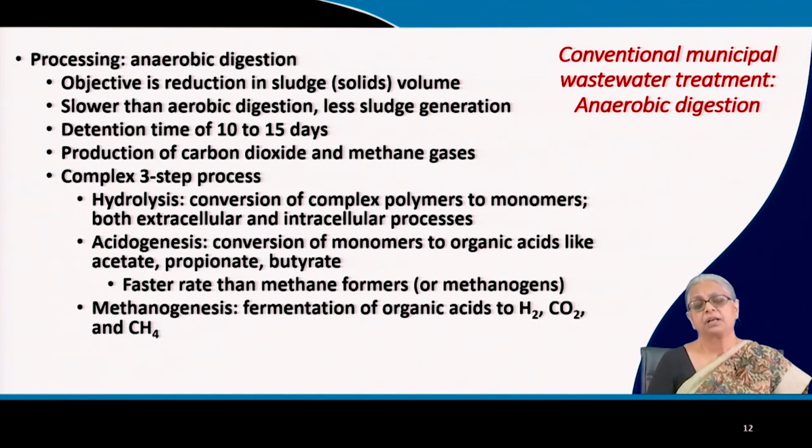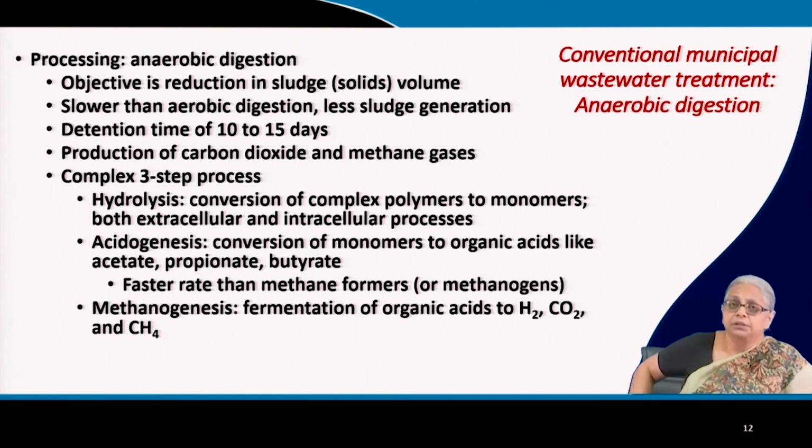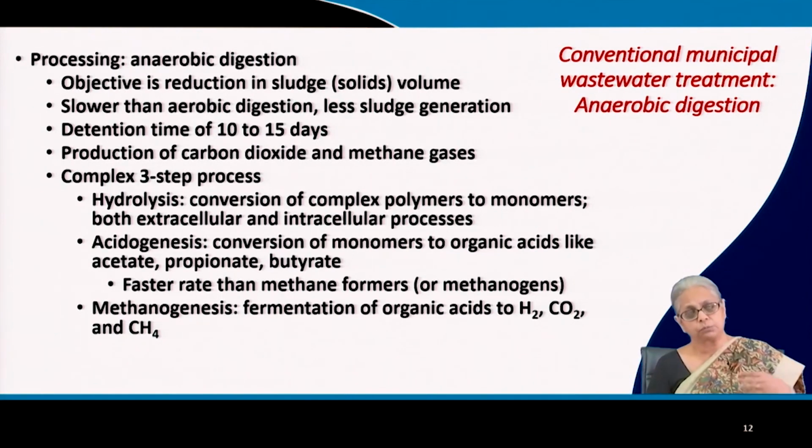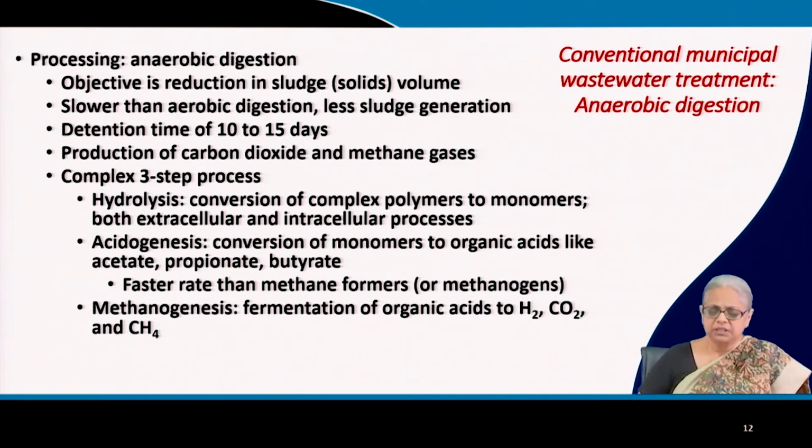Now, if you can imagine a large city and a wastewater treatment plant for such a city, that's a huge amount of both water as well as material that needs to be taken care of. So by reducing the volume, or rather, let me put it another way, by increasing the solids content, if you can go from 1% to 5%, 10%, 20%, 20% seems to be the highest, you can reduce the volume in terms of the water content enormously.